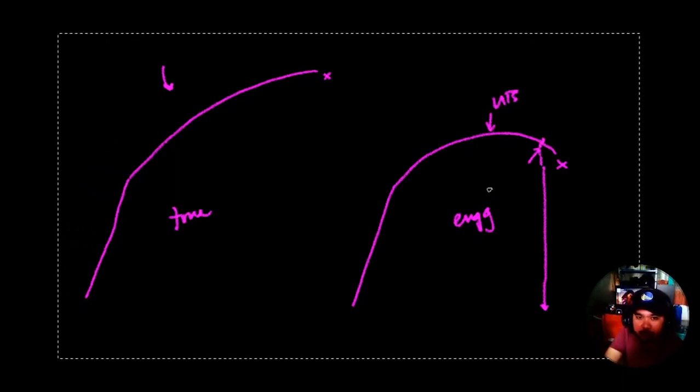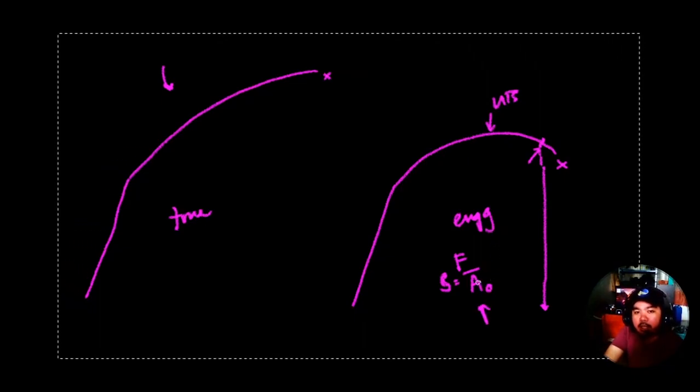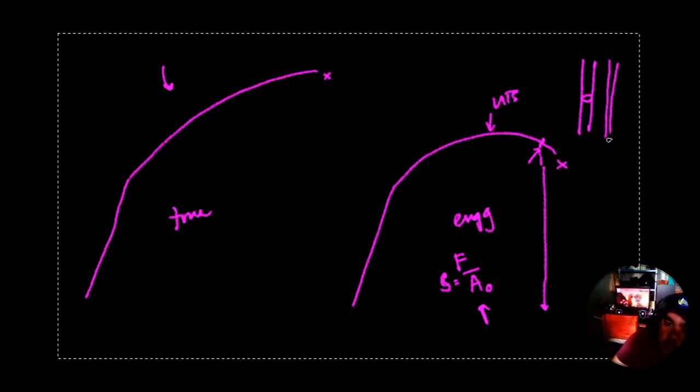So the fundamental na siguro flaw dito sa engineering stress strain diagram is the formula for engineering stress. S is equal to F over A naught, where A naught is the initial na area. Pero take note that when we are deforming your metal, so for example from this area, when we deform metals, it becomes thinner and thinner, no? So A is not actually a constant, tama?